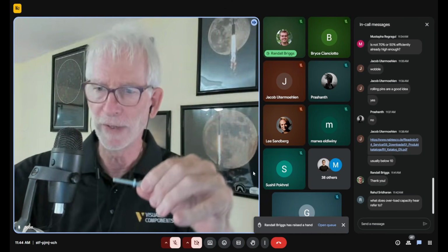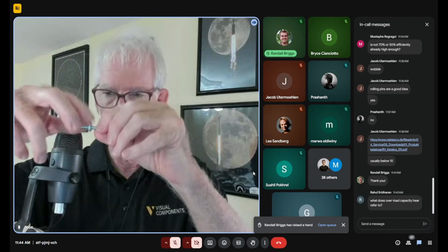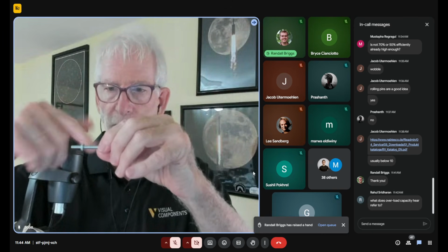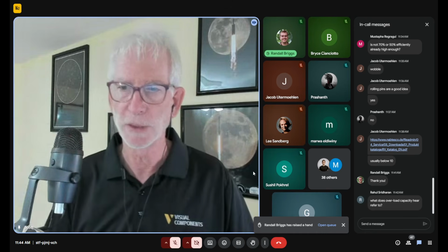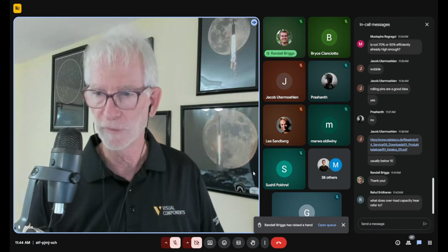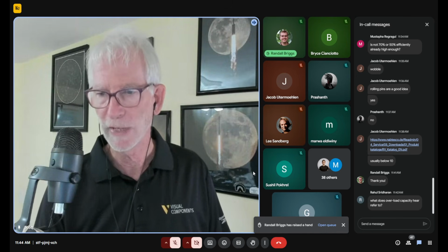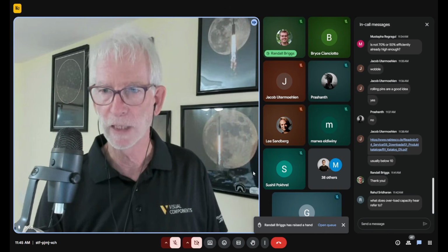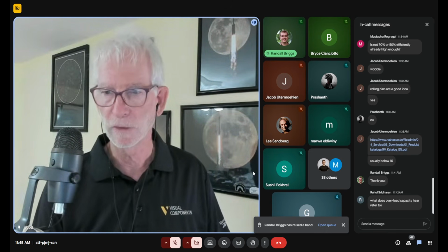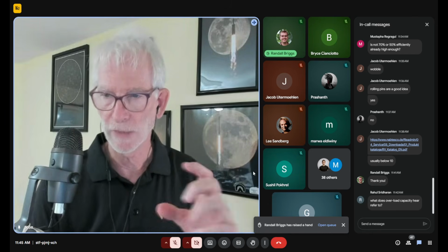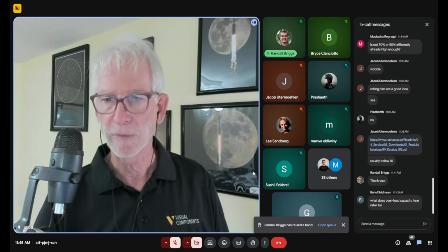Now, we all know ball bearings are a great solution for reducing friction when you want to have two objects rotating around each other. And so this is sort of the idea of a ball screw bearing, is that the balls go in there and they recirculate around, and they basically are in the threads, and they produce a lot of stability, and they also get rid of the friction. So the nut is made out of something like that.